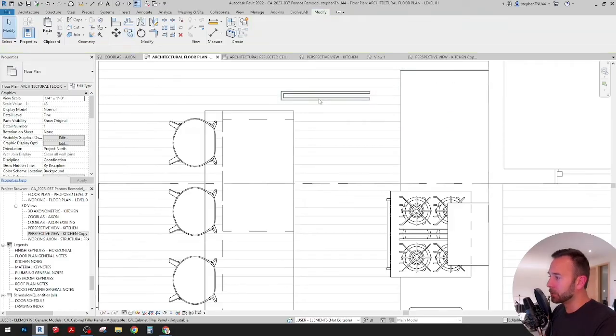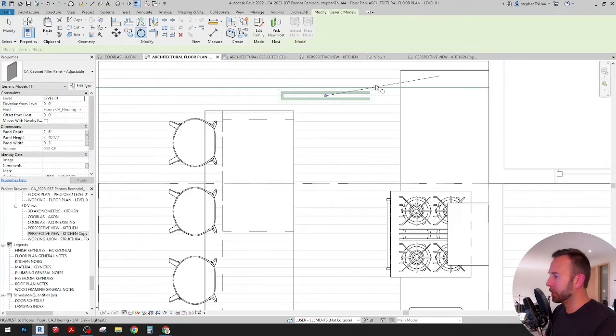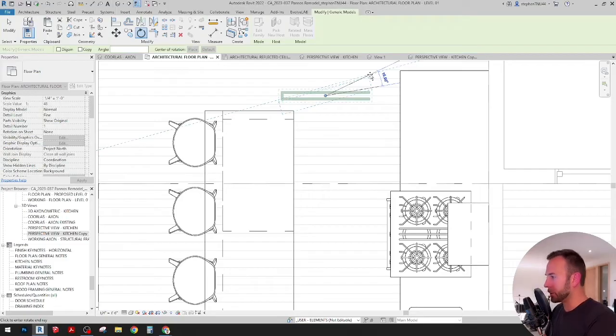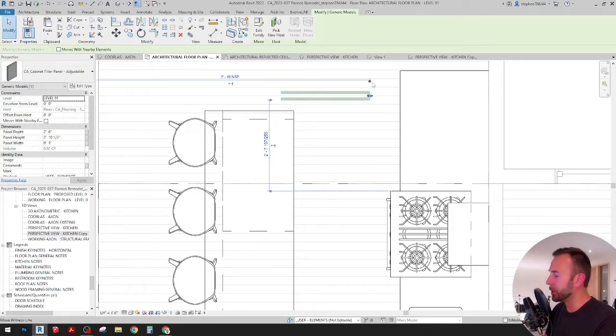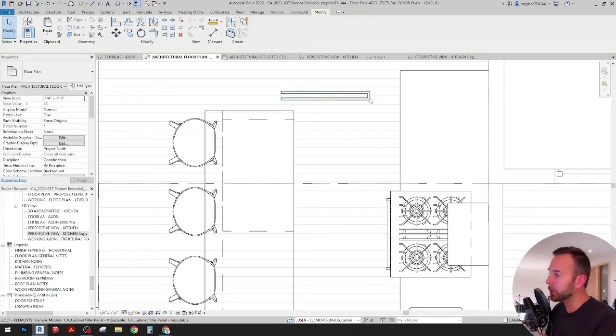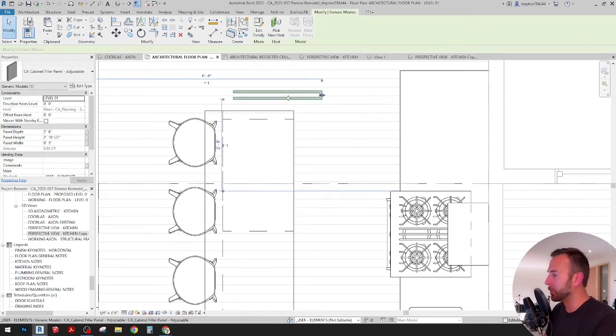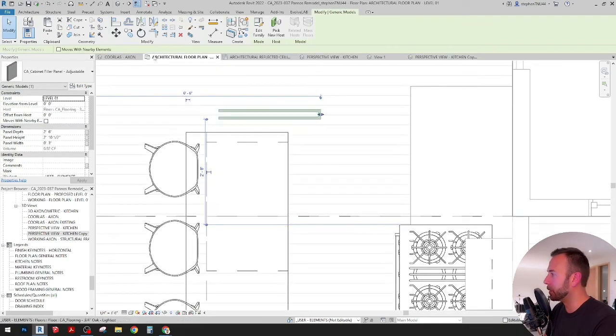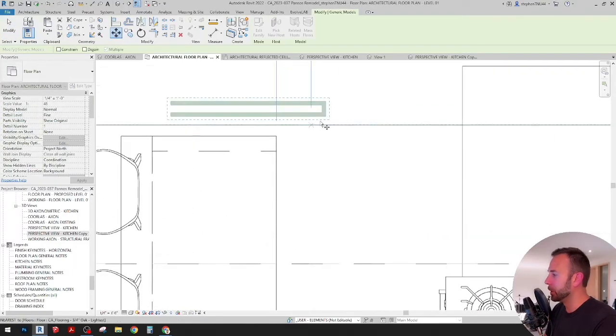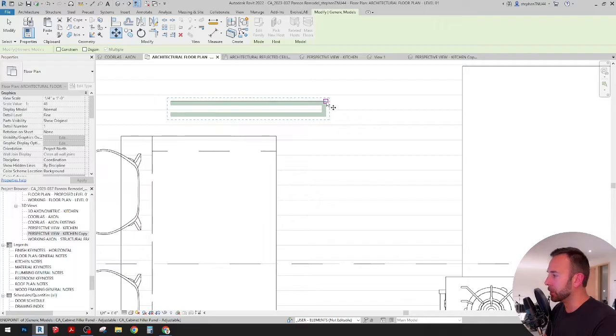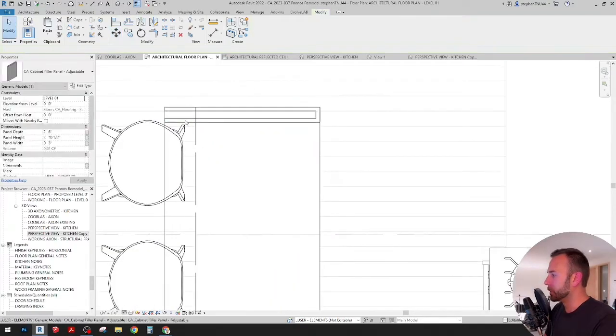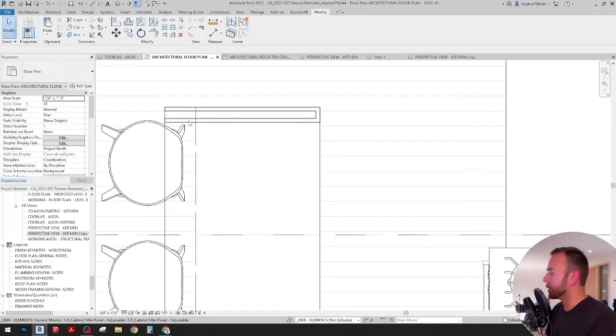Typically in custom kitchen construction, you'll get these end panels that are constructed that look like this. And I've also found that it gives me a little bit of flexibility. If we did need a few extra inches here and there, I can always convert this to a single 3/4 inch panel. And, by eliminating 2 of those, you've gained easily another 3 inches on one of your cabinet sizes. So just as a starting point, it's always nice.